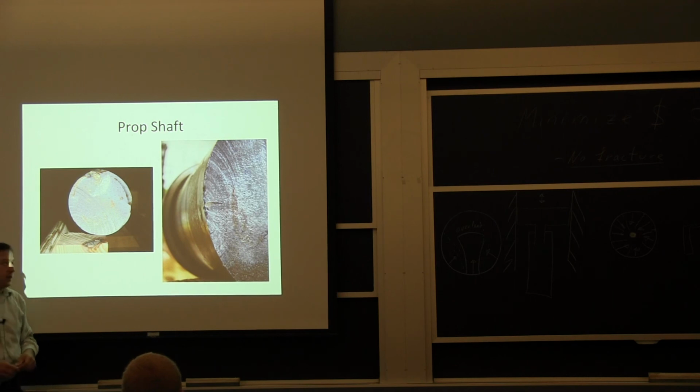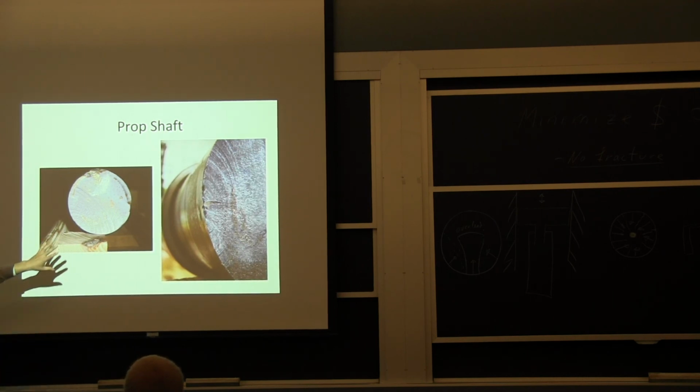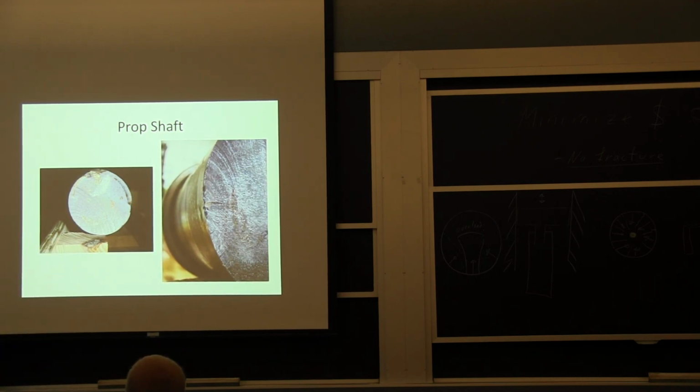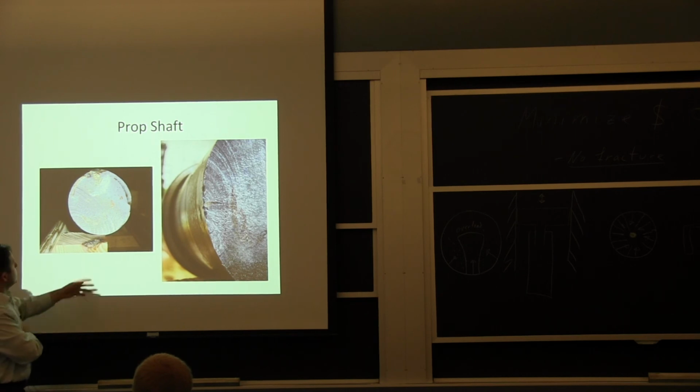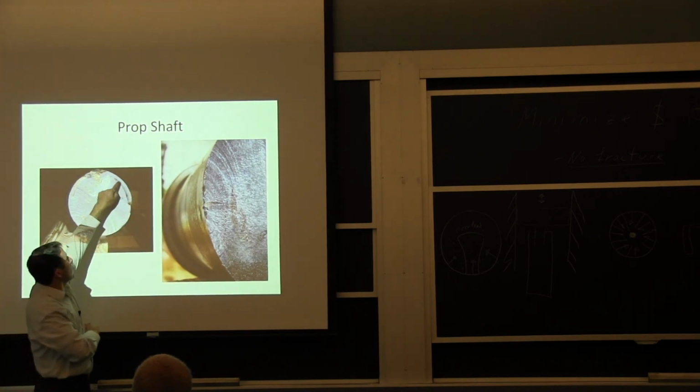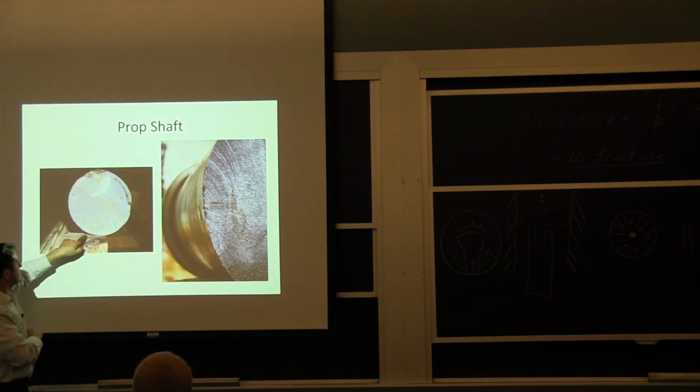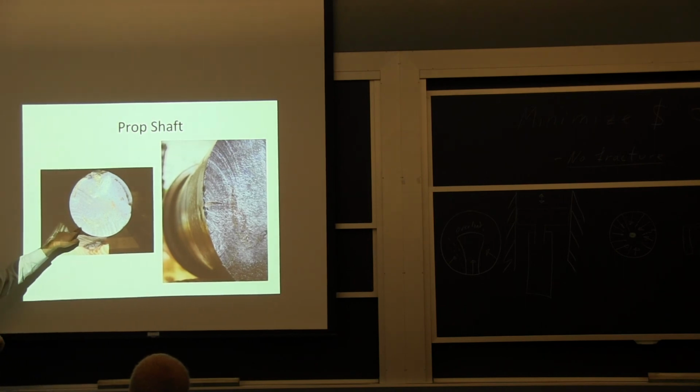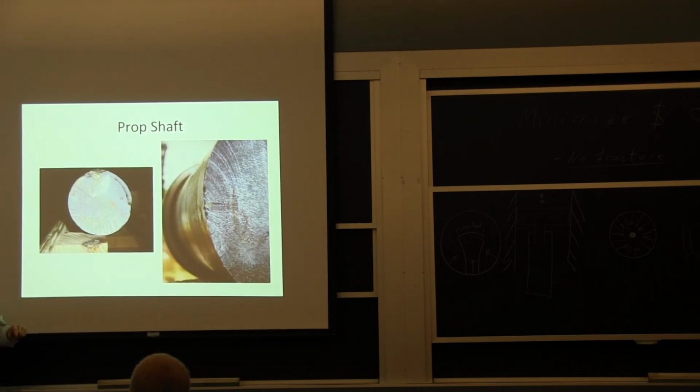And the significance of that in this particular case is if there were gouges all around the axle, I'd have initiation sites everywhere. Because I have just one there, the load was the same as you keep going all around.